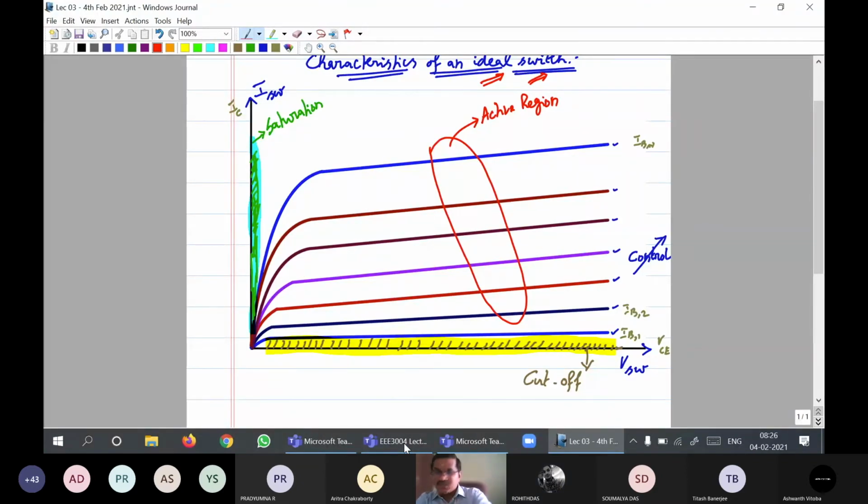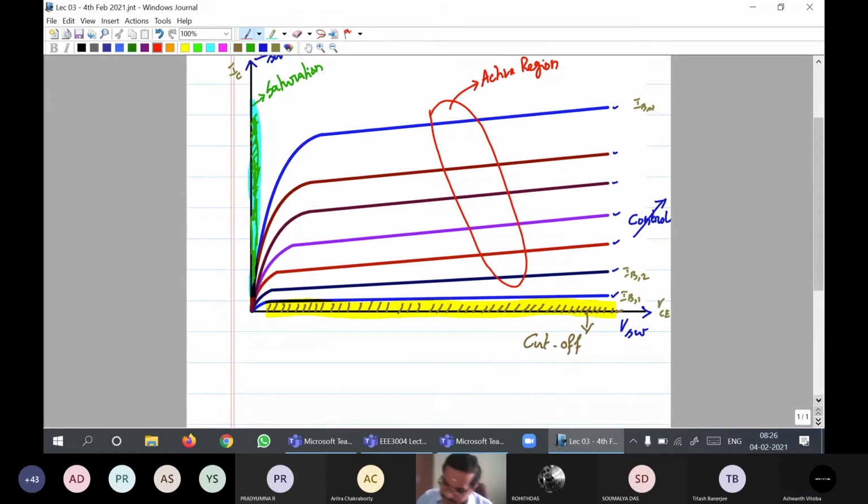Okay. So when the switch is on, what can you expect? What electrical parameter is going to be important? When the switch is off, what electrical parameter will be important? Current, sir. Good. Current during which state? On state. On state, you are thinking about current through the switch. Saturation region. Excellent. So off state, you will be thinking about off state voltage across the switch. That's all.